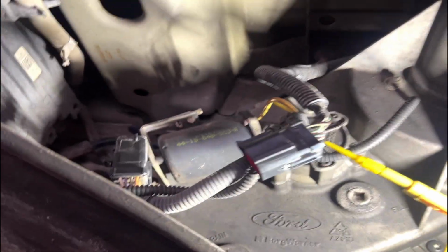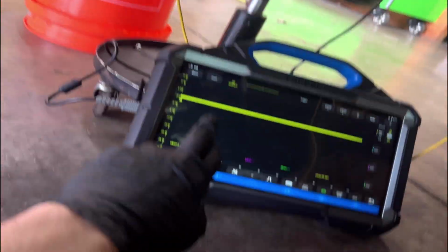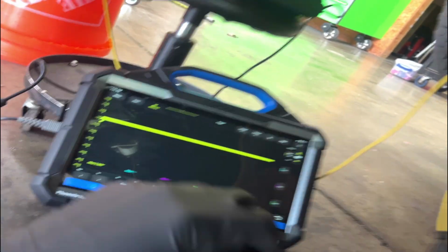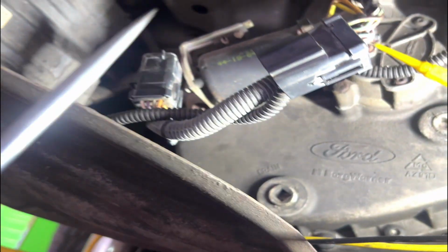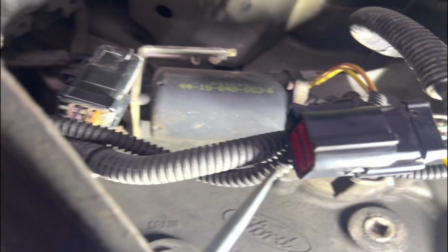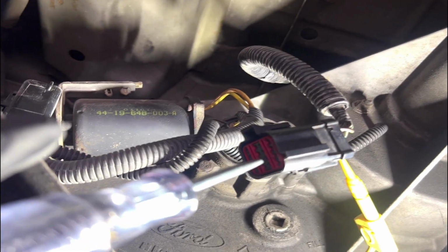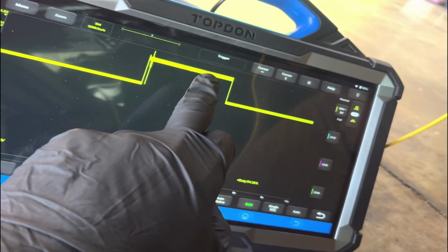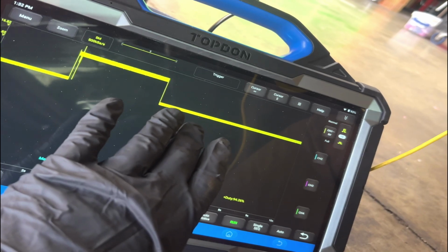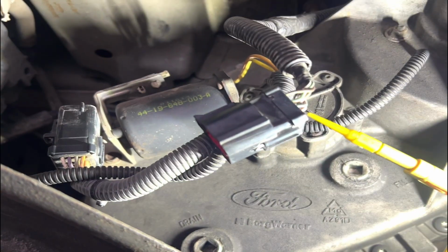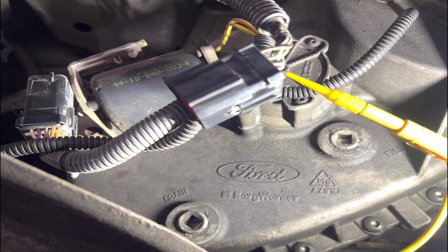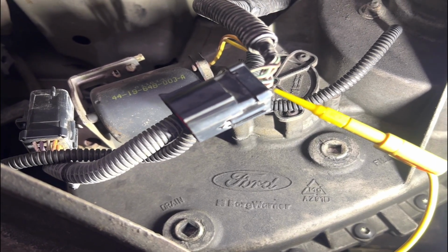Let's get our scope on there too. Let me set it up. All right, we're back probed in there. Scope is at the 2.3 volts or whatever. And then the other end of this test light's hooked up to positive. I will just touch on this pin, make sure we have contact. Again, it's a big round pin in there. And you'll see we jump up to 12. So it's not a strong ground. This is just a very light signal ground, it appears.